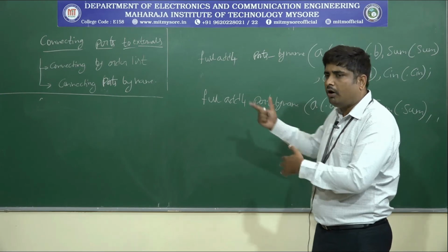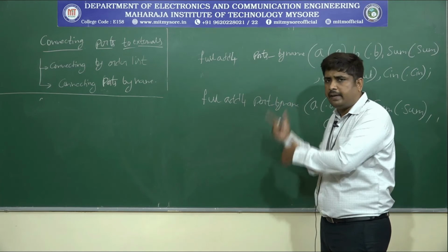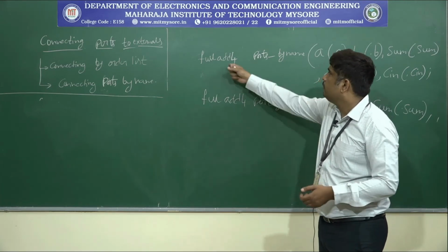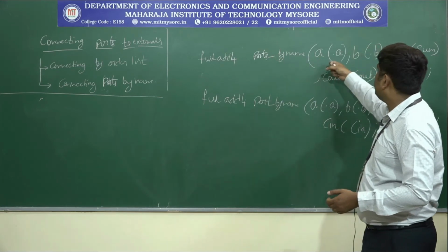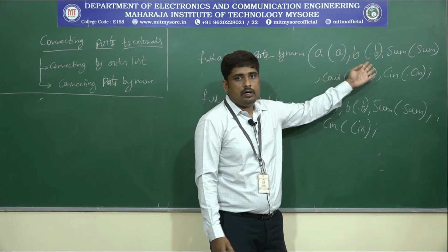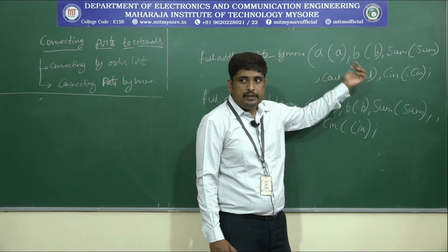instantiation. Okay. So all those things, module, input and output, are the same. There is no change. Directly go to the instantiation, full adder with port names. So here A dot A, then B dot B, the same name. Earlier the order was the same, but here the name should be the same.